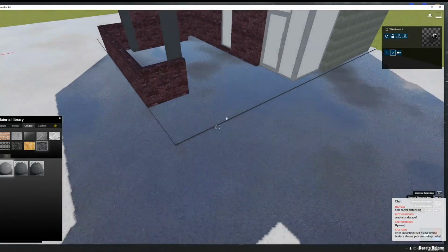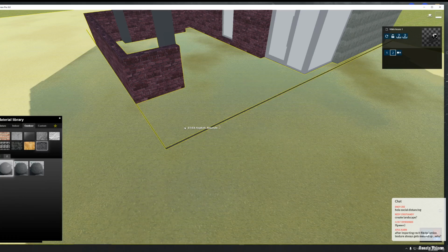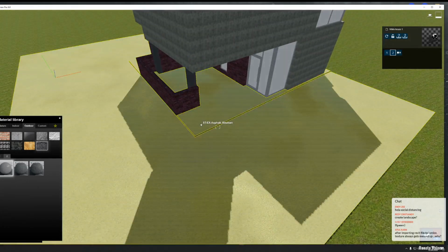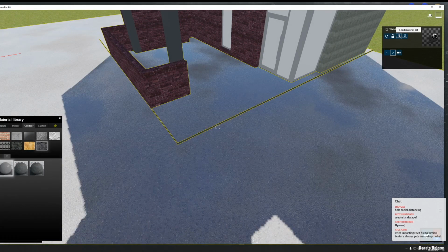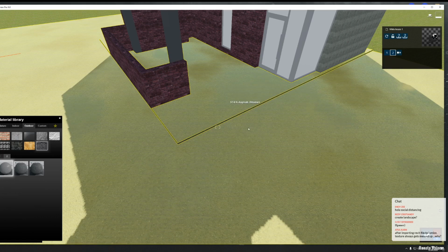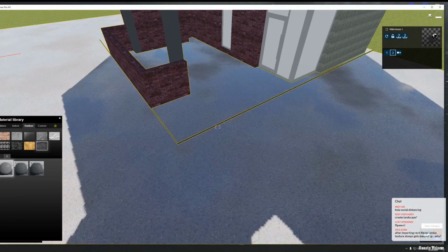And the nice thing we get, as you can see here, is the same materials. That's why, remember, last time I said we will change all materials. Why am I saying that? Because if you are using the same material like here, Lumion will understand it as one material. As you can see, they are different elements but one material, and that's why once you apply asphalt here, you will get asphalt on this side too. This is a terrible thing. So what are we going to do?